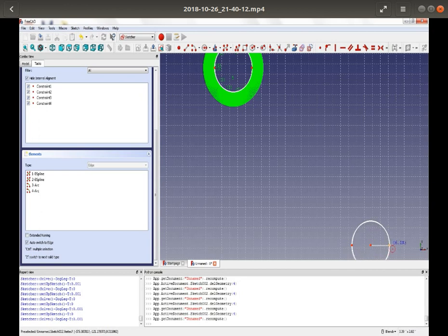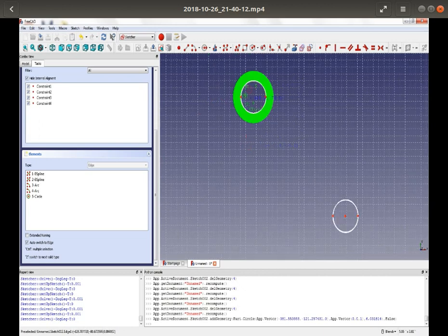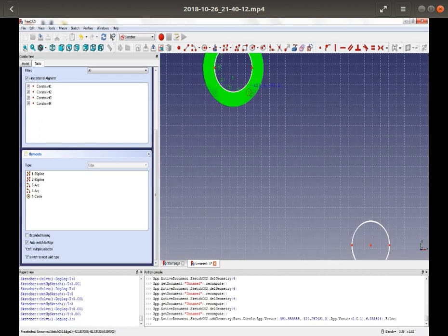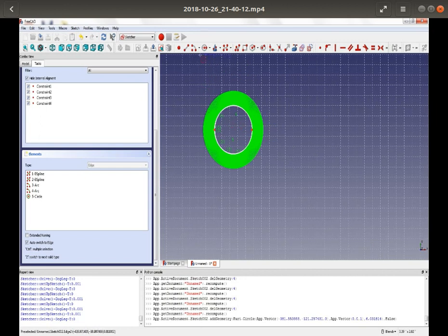And if it's a peck cycle, it's still going to peck that drill down on the material, and you're going to be happy as a clam because it's drilling right where it's supposed to be. But it's too big or too small of a hole because, well, the CAM package doesn't care what size bit is in the actual holder. It's just going to generate your code for you.